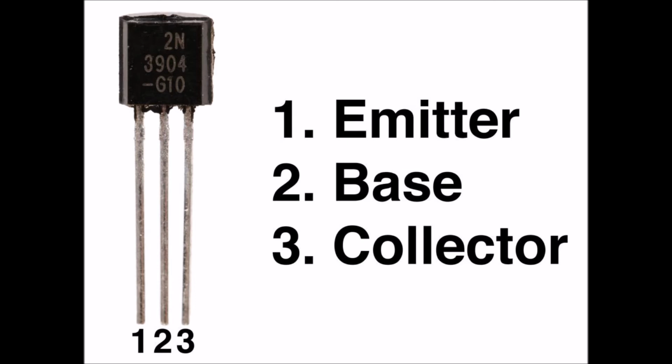This little bit of signal leakage can provide enough energy at the input to cause the whole circuit to chase its own tail. When positive in-phase feedback gives rise to oscillation in an amplifier, we say that the amplifier suffers from parasitic oscillation, or parasitics, which can cause a radio transmitter to put out signals on unauthorized frequencies or make a radio receiver stop working altogether.